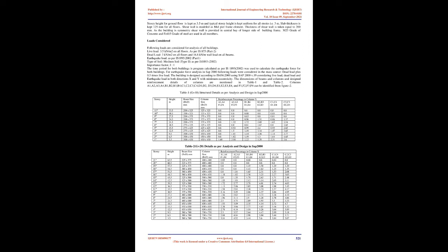Methodology. Performance-based seismic evaluation of buildings is carried out using pushover analysis. It is a static nonlinear procedure in which the magnitude of the structural loading is incrementally increased. With the monotonic increase in the magnitude of the loading, weak links and the failure modes of the structure are found. As the load and displacement increase, the elements, beams, columns, etc., begin to yield and deform inelastically.